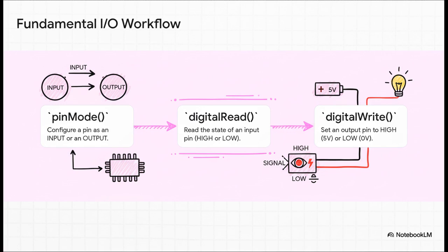The basic digital input/output. It's really a simple 3-step dance. First, in your setup code, you use pinMode to tell a pin what its job is. Is it listening for a signal? That's input. Is it sending a signal out? That's output.